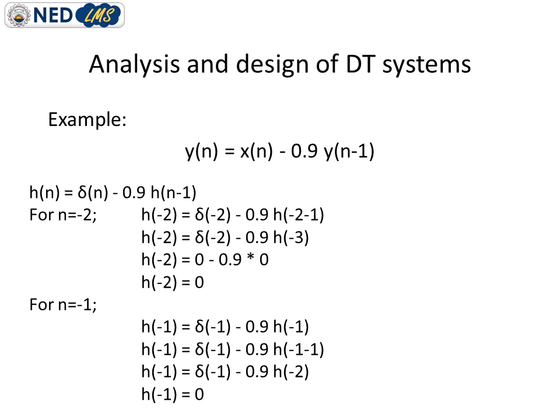We first transform our equation into the impulse and impulse response. The impulse is considered as an input, so x of n is replaced by delta of n, and y of n and the delayed version of y of n, which is the output, is replaced by the impulse response. So here y of n is replaced by h of n, and x of n, which is the input, is replaced by delta of n, which is the impulse function.